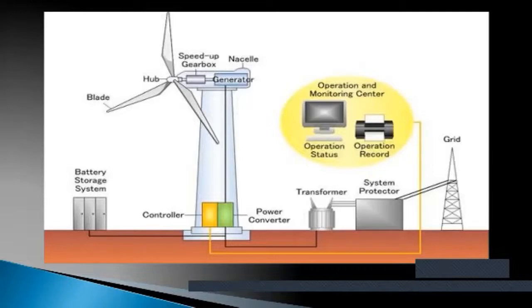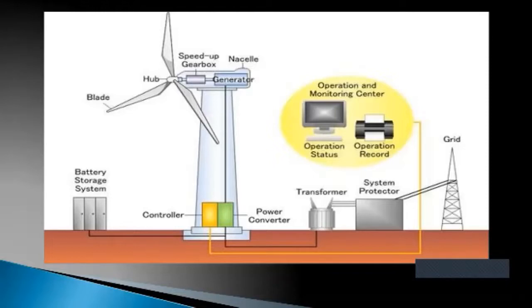The gear assembly is used because the wind speed is not very large, and for generation of power we require near about 1500 rpm speed. At that speed the generator is not rotated directly by the wind. That's why the gearbox assembly is used to increase the speed, since the wind speed is low. The wind blades rotate slowly, but by using the gearbox assembly we change the speed of the generator easily.